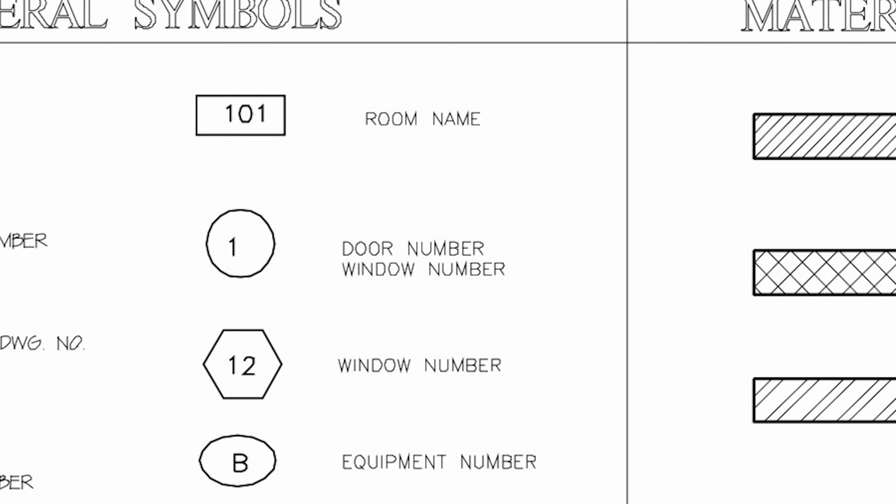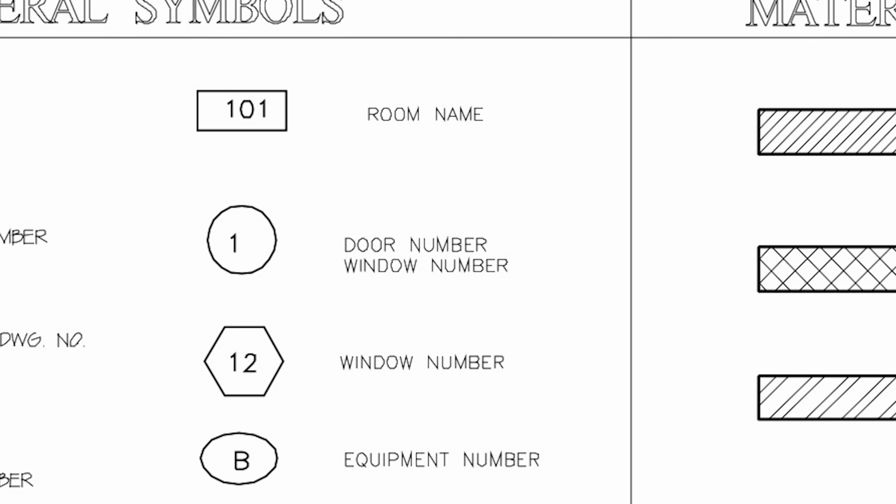And why do we put symbols like that on drawings? We put symbols like that in order to show a relationship, a connection between certain drawings, for example, the door schedule. We have a symbol for the door schedule, and on every door we just show the symbol, so we don't have to repeat things over and over. You know that symbol represents the door.